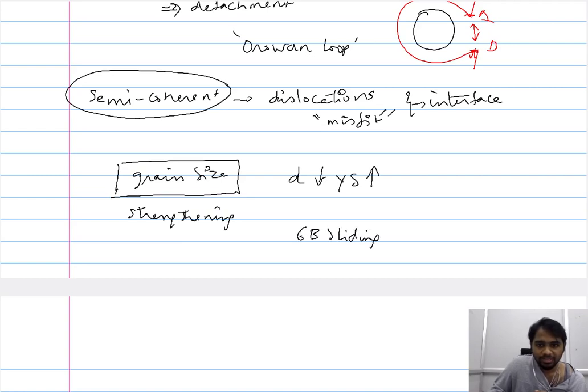We saw in the previous lectures that the grain boundary is nothing but the interface that separates two crystalline grains. Therefore, the grain boundary in itself is not crystalline in nature. And when you raise the temperature, it behaves like a Newtonian viscous fluid. So when you have a grain boundary at high temperature, which is not crystalline in nature, it behaves like a highly viscous fluid and it begins to glide under the given mechanical condition.